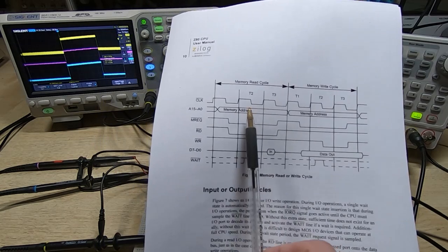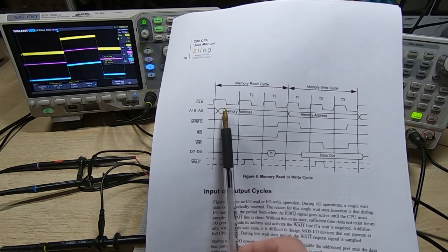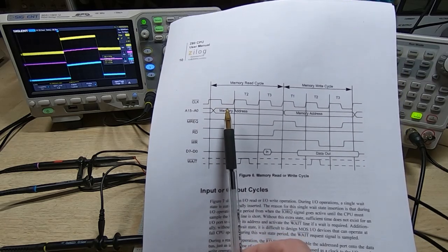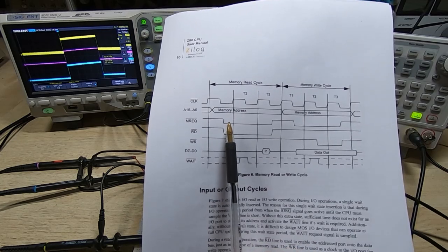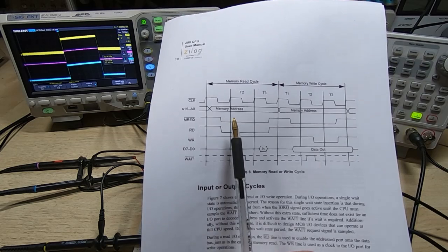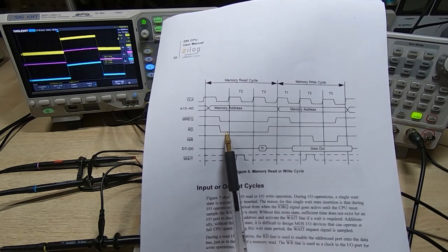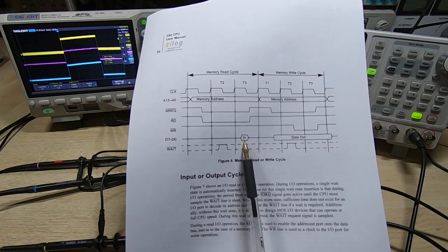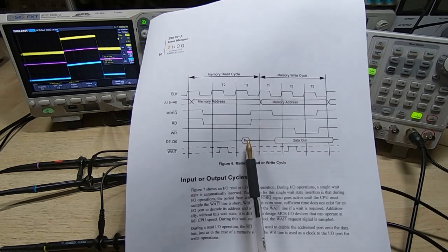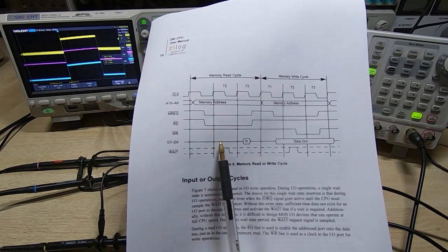So for example, let's say we want to do a memory read. Then from the point where the clock falls in the T1 cycle of the read cycle, you have a finite amount of time to respond to the memory request and the read lines going low to set up your data. And that's the data usually coming from something like a RAM chip or something like that. But this time is dependent on the RAM chip.